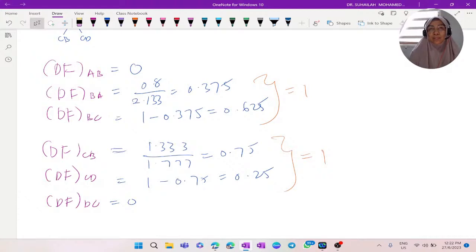One important thing is the support condition, because we calculate based on the K formula, considering the far end condition. For a far end fixed, we use 4EI over L. For a far end pin, we use 3EI over L.